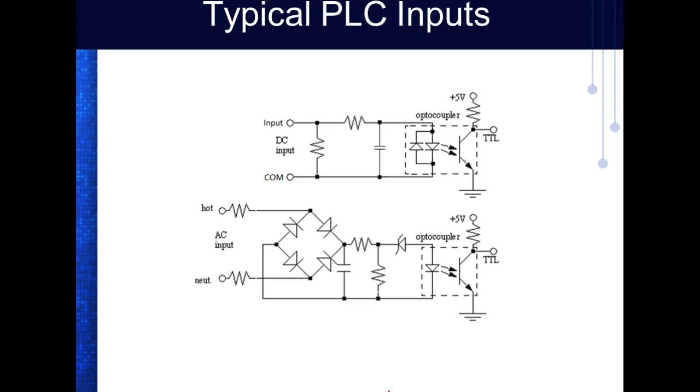So that means if something happens, if we didn't put that optical coupler right there, you could have something happen on one of your input ports, and it could wipe out your whole PLC. Just blow it up. But if you screw up real bad, it might blow up the optical coupler, but it doesn't hurt any of your other ports. So we do it in there to prevent what we call massive failures because we screw up something like that.